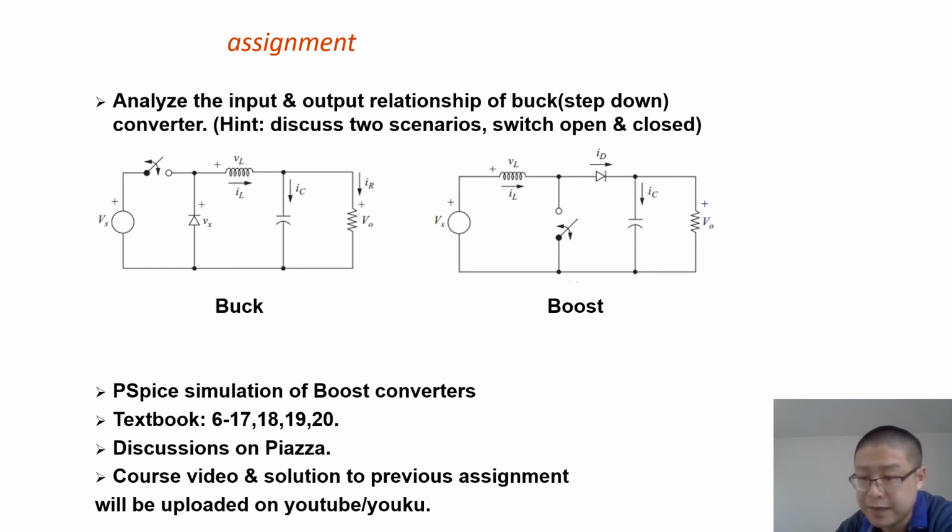Using the fact that the circuit is operating in steady state, so that the net change of inductor current in one period equals 0, we can derive the relationship of input and output voltage. That's how we analyze the boost converter.